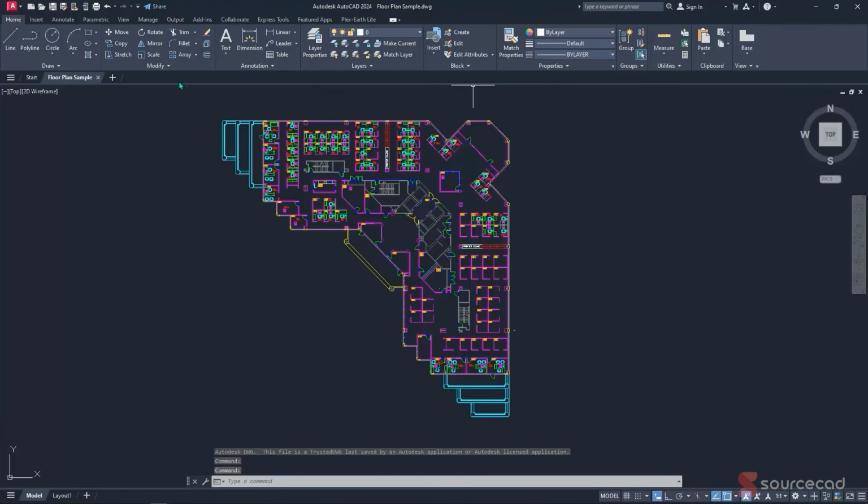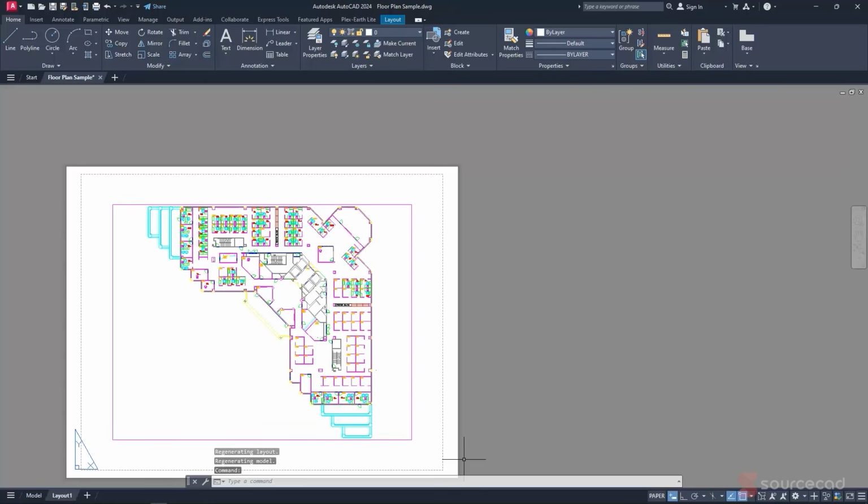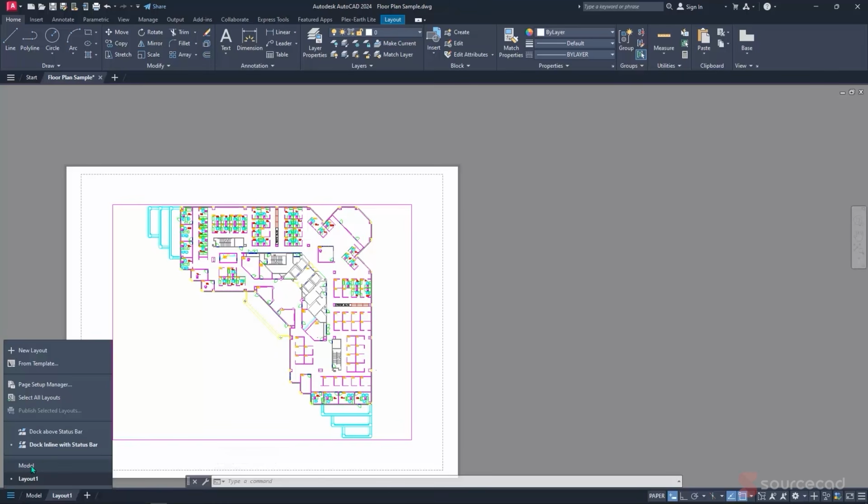So basically, this is just our workspace, which is basically an unlimited, infinite drawing area that we can actually use to draw using these commands here and manipulate using these commands and so many others. Not only that, at the bottom left corner, you'll find this model and layout. So this basically changes our view from model to layout, which is basically paper, and you can actually see paper over here. And if I wanted to go back, I can either click over here or I can click on this option and navigate to model.